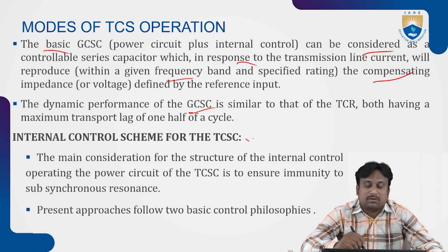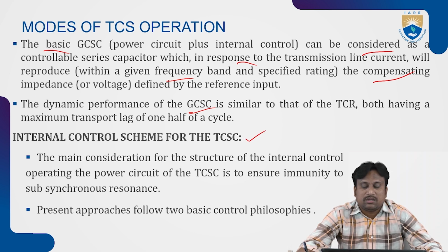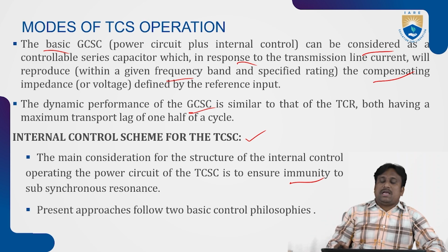So the internal control scheme is presented here for the TCSC. The main consideration here is the structure of the internal control operating the power circuit of the TCSC. This is to ensure immunity to subsynchronous resonance. The present approaches follow two basic control philosophies.